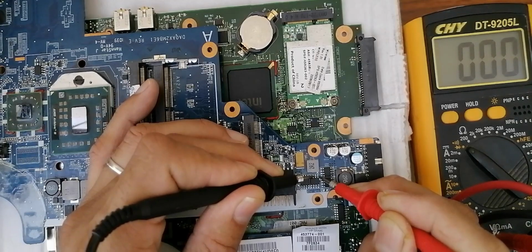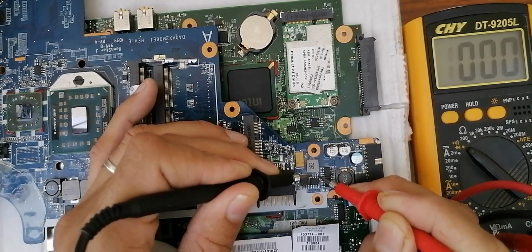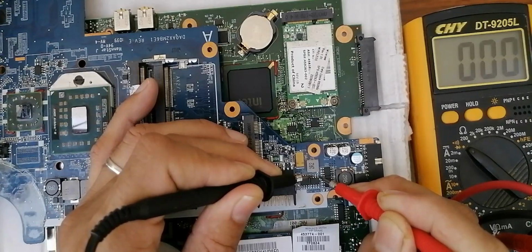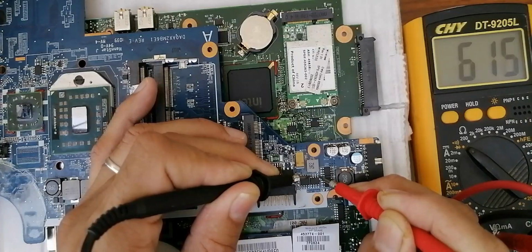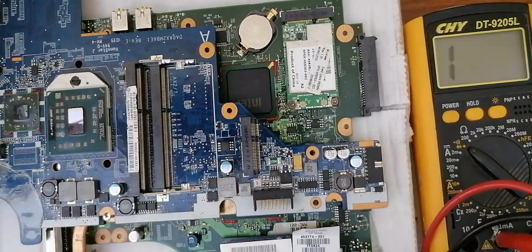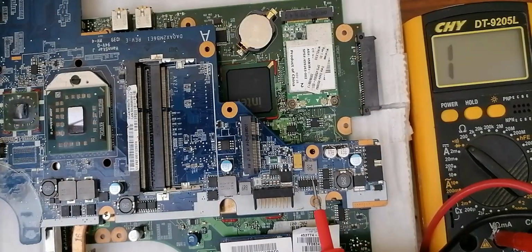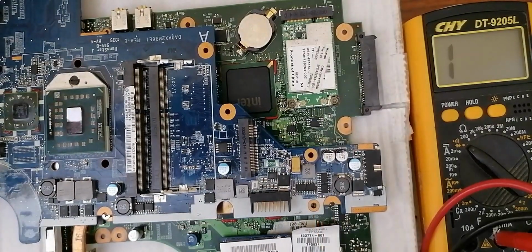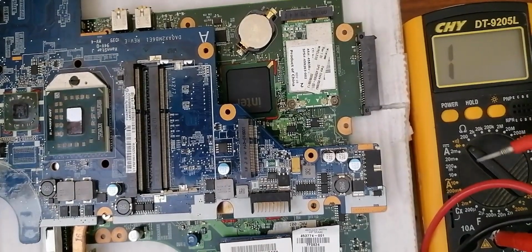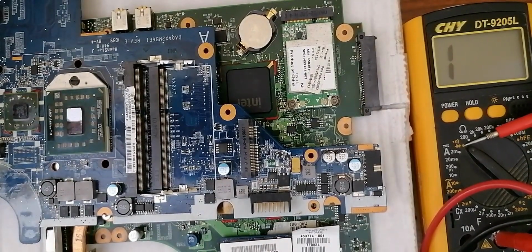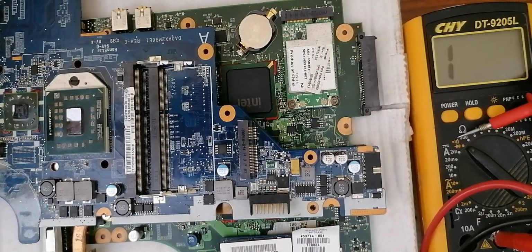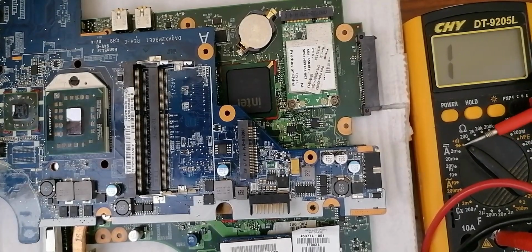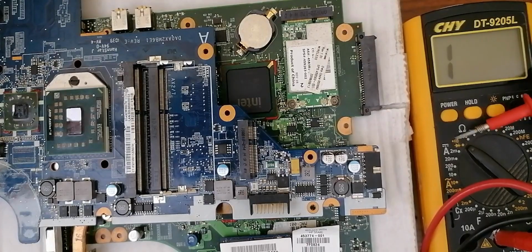We get continuity on the multimeter and a beep. So let's check the other pin. The 3rd one, we get continuity. The 4th one, nothing on the multimeter. We didn't get continuity because this is the gate. So these 3 pins are connected together. So this is the source. By the way, here I put the multimeter in the diode option, but of course to check the continuity we should select the continuity option, the buzzer. But in this multimeter the diode option and the continuity option are in the same place.